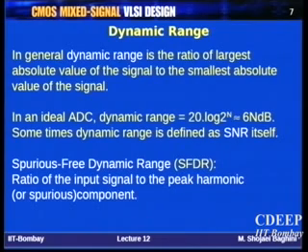Acceptable is that, tomorrow you may be okay with an SNR of 20 dB. Somebody else may like to have an SNR of 40 dB. Therefore, that defines your dynamic range. So, this is a general definition of dynamic range. Now, suppose you have an ideal ADC with n-bit resolution. Therefore, the maximum signal you can have will be full scale. The minimum signal you can have will be LSB. Therefore, the ratio of them will be 2 to the power n. So, therefore, in an ideal ADC, dynamic range is 6n dB.